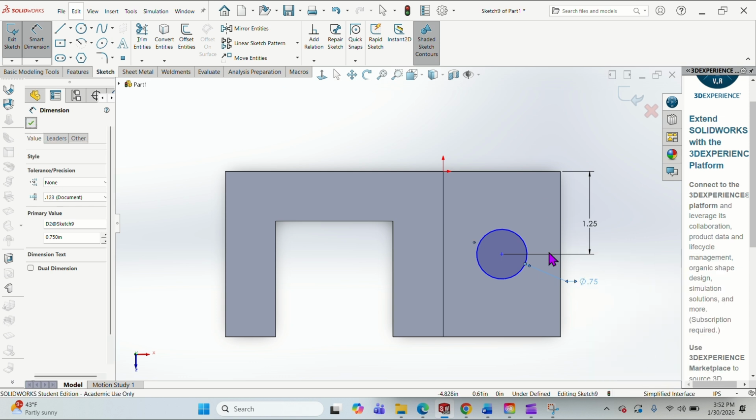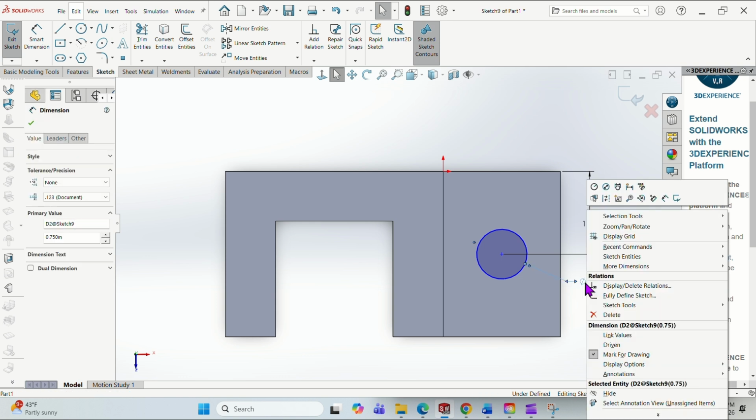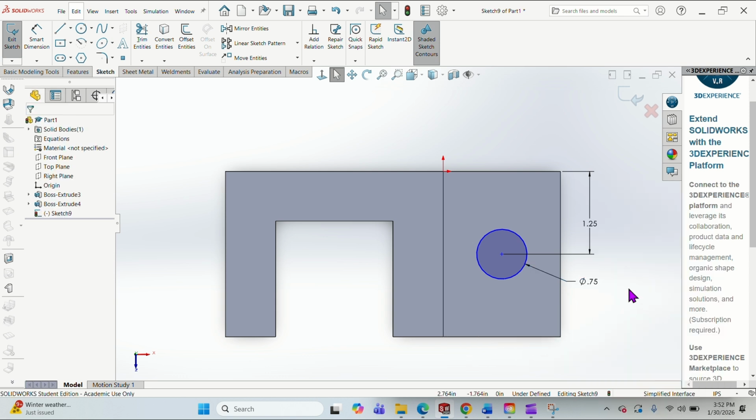Now, let's just say yours is R, and for whatever reason display as diameter is not showing up. You can go to display options and get it from there too. Okay, two different ways. It doesn't always pop up the way it did the first time. Usually you have to go to display options and change it, but we want it as diameter.